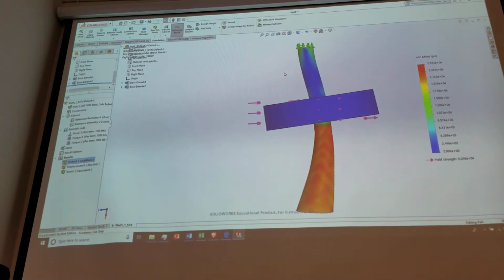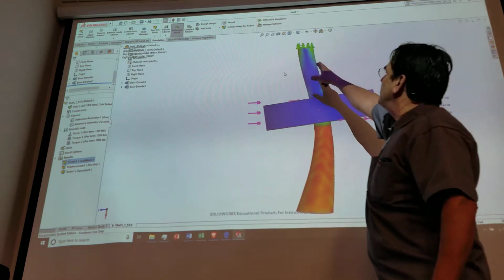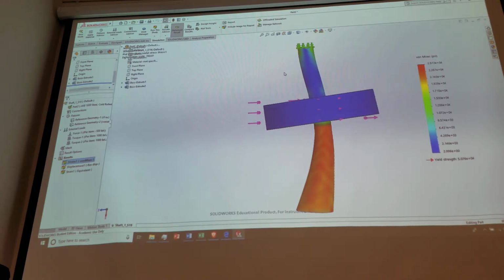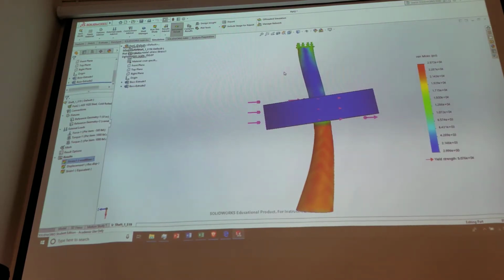Because what did it do up there? It shows almost no stress at all. Well, it should have up there. By the time it gets to this end up here, what should the stress be? It's the free end, right? It should be zero, because what's the bending moment going to be by the time you get there? The bending moment's going to be zero. There's no torque up there, so on the outside surface it should be pretty darn close to zero.